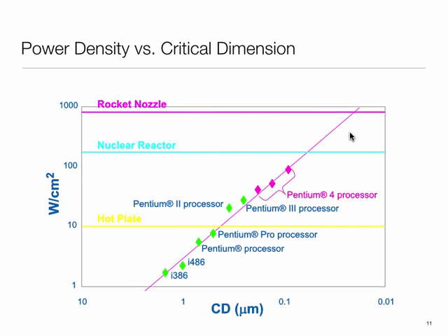So the idea is that I couldn't afford to use that silicon because of thermal reasons. Might as well use it for the specialized processor so that on average then I come out ahead. Okay, so not just do I have more cores, but I also have cores that are specialized, because in any case I will not be able to keep all of them alive because of power reasons.